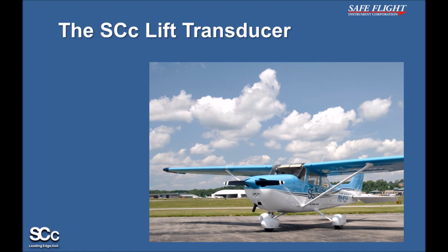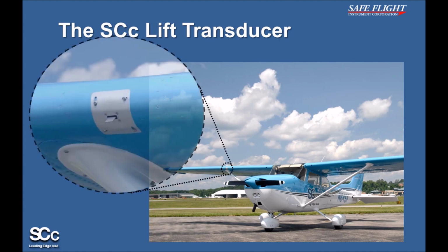On this aircraft, you can see the mounting location of the Lift Transducer. It is important to note that Safe Flight's Lift Transducer is the only angle of attack sensor on the market that measures the wing's leading edge flow, an exact analog of the lift coefficient that angle of attack determines. I'll explain why this is important on the next slide.